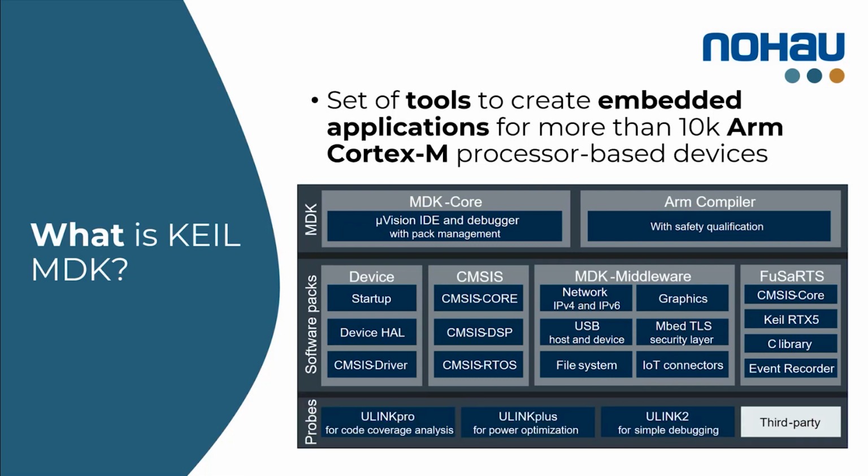And lastly, the probes. MDK supports many different debug and trace adapters. So you have ULINKpro, ULINKplus, ULINK2. And ULINKpro is for instruction trace-based code coverage and performance analysis. And that's the one that we're going to be using during the demo.